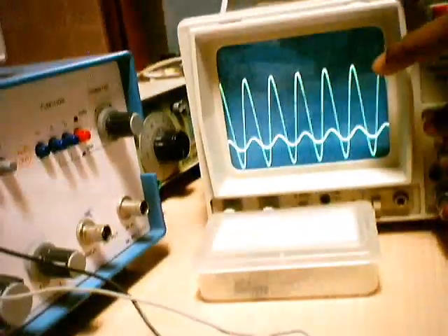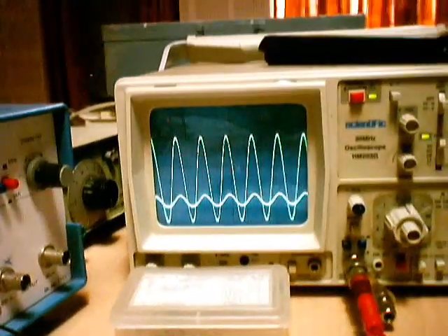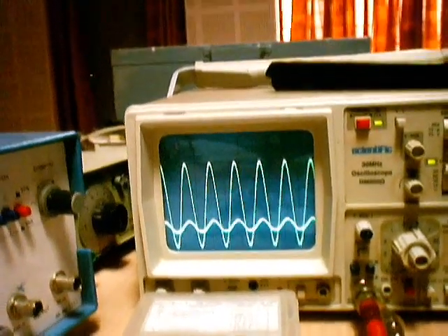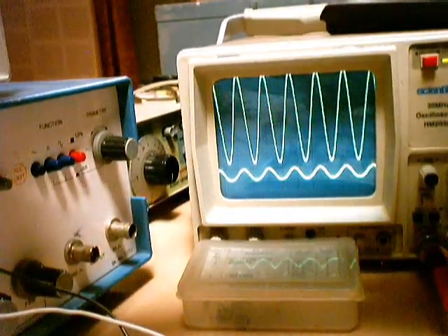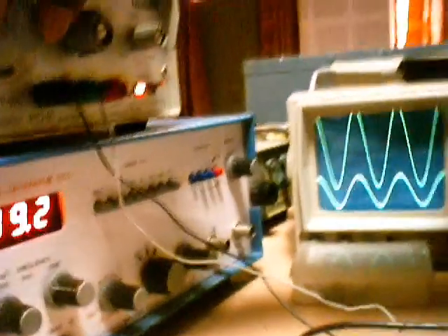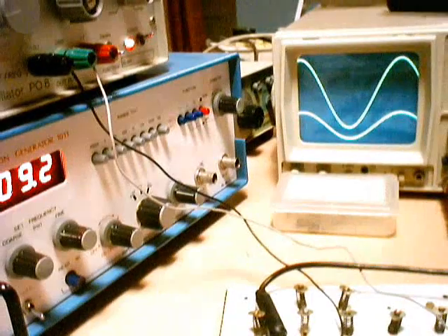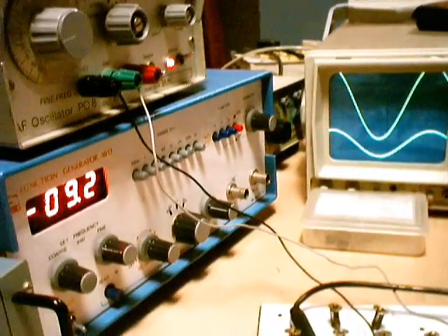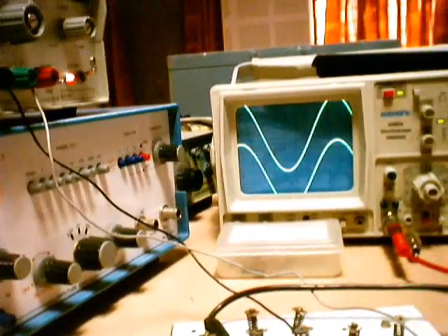So this is around 12 volts, 6 divisions into 2, so the input is 12 volts. Now you can vary the frequency. Before we start taking the reading, let us verify whether the band stop action is happening or not. The frequency is now around 2 kilohertz, because we are expecting the center frequency of the narrow band stop filter to be at 10 kilohertz. At 2 kilohertz, the output amplitude should be equal to the input.